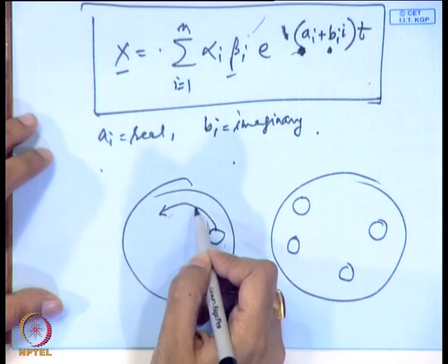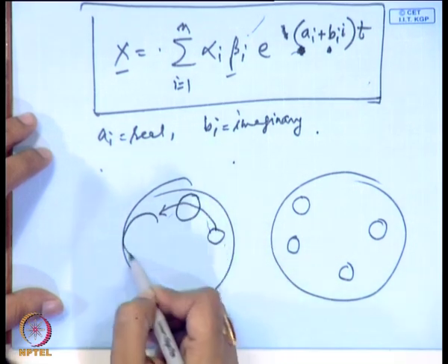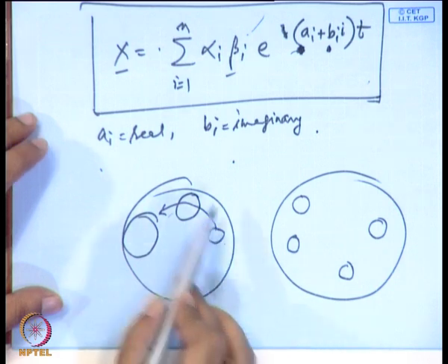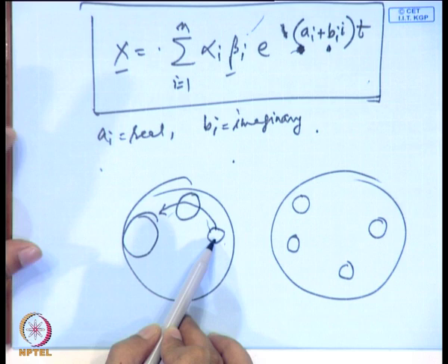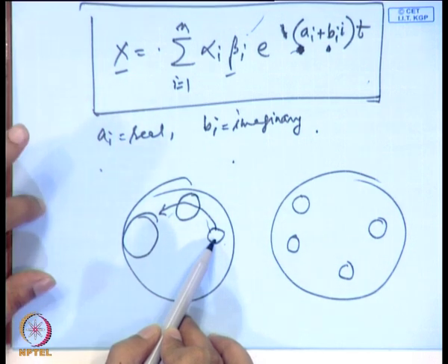a small region in the reactor where the temperature grows suddenly, and then it starts to gather in space. For example, if you started over here and then it goes over here, it becomes like this, it goes over here, it becomes like this. So, this is how a hotspot is generated. A small increase in temperature is a major problem. You can have concentration hotspots also, but temperature hotspots are a major problem because they lead to the reactor blowing up.